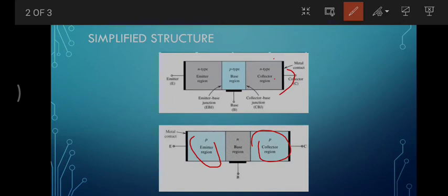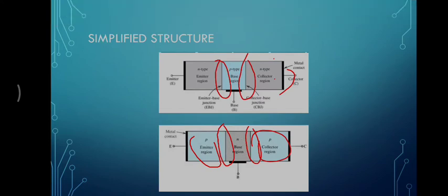If you look at the circuit more closely, the transistor consists of two PN junctions. One PN junction is here and another PN junction is here. The reason we call them bipolar junction transistors is that they have two PN junctions. Depending upon the bias condition, forward or reverse, these two junctions give different modes of operation. So we will look at these operations quickly.